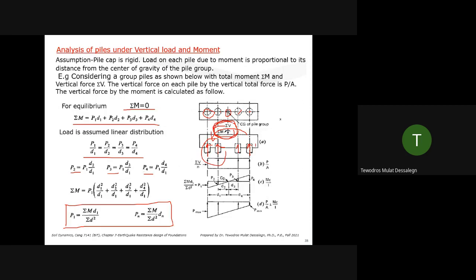Either a structural engineer will give you the loads at the foundation level, or you could estimate it. If you assume a single degree of freedom system, like a 1-story, or the whole structure is a single mass, then you can use response spectrum. Response spectrum is assuming the entire thing is a 1 degree of freedom system.